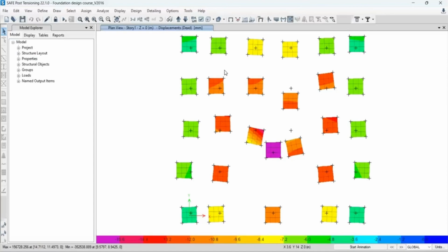Okay, so you need to make sure the bearing pressure you are getting from the service load combination is lesser than the SBC, that is the safe bearing capacity of your soil. If this is lesser, meaning it passed the soil bearing pressure check, and your foundation is not going to sink, right? Your foundation will be large enough to distribute the building weight without overloading the soil.